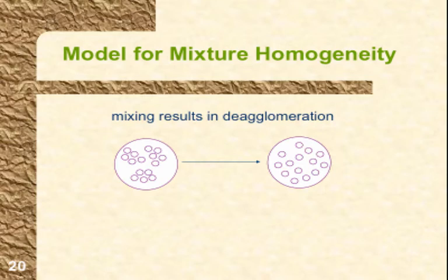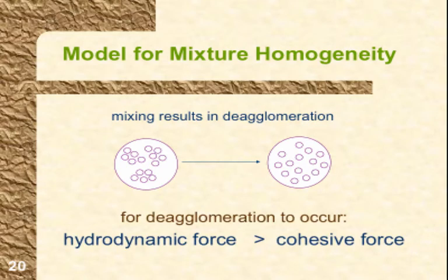So you have agglomerates, they need to break down. That's what the model has to be capturing. You have different particle sizes, right? And so smaller particles, higher surface area, they might agglomerate more. More particles clustered together might need a higher shear rate. And then, of course, you change the polymer by changing the viscosity, right?